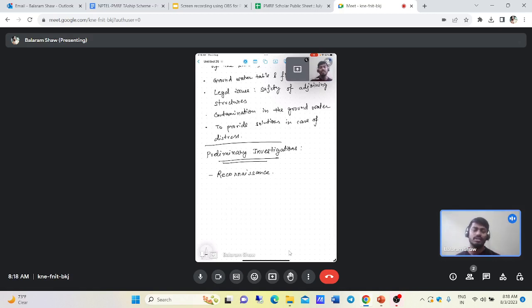And after that, after choosing a site, or two or three, reducing the number of alternatives to a few, then we will go for detailed investigation, because in the detailed investigation we have to incur some cost that will be somewhat more expensive than this preliminary investigation. So that's why we have to do the preliminary investigation first. In preliminary investigation, we have to do a reconnaissance survey, then we have to study the maps, and then the aerial photography. Nowadays, for the big projects, we have satellite data, and we also go for remote sensing and satellite images, and then we can analyze easily, right?